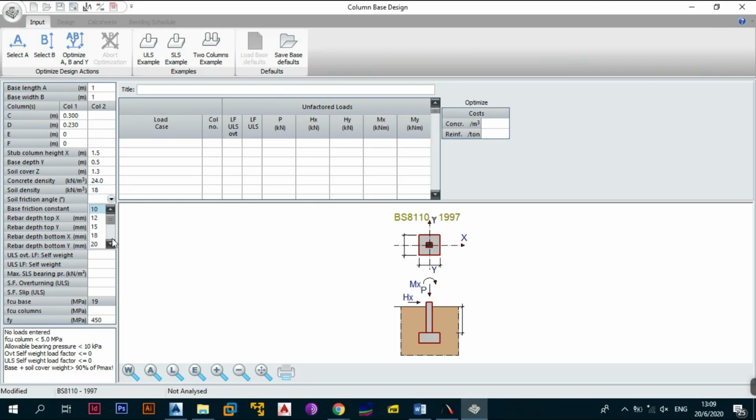Next, you have the soil friction angle. This one is the internal friction angle for calculating the passive soil stress. This is also obtained from the geotechnical report. But I'll tell you, from sub-Saharan Africa and dealing from where I am currently, the average angle is about 20 to 25. So I'll use an average of 22, which is what we will use for now.